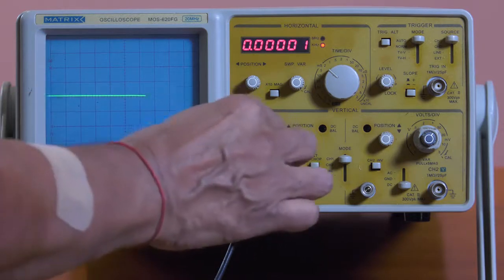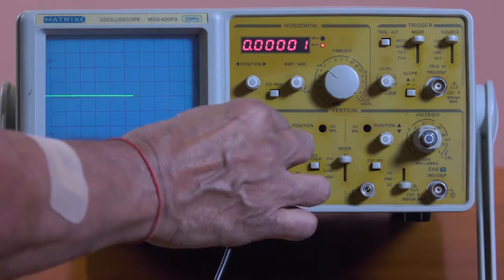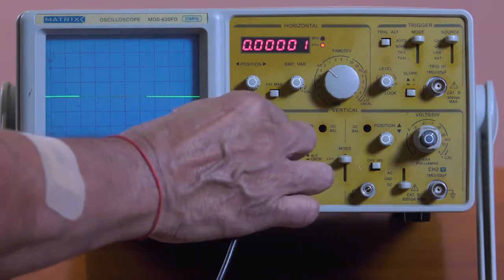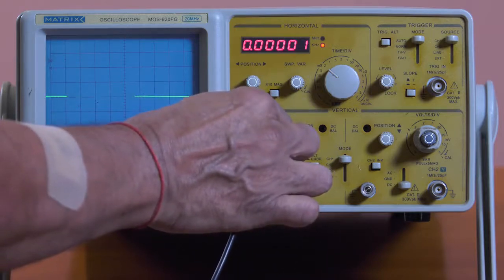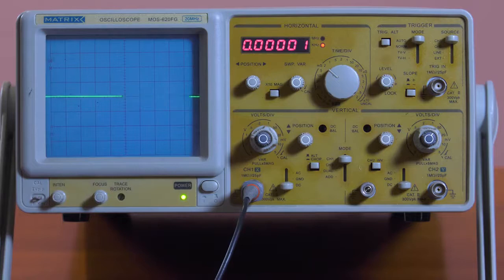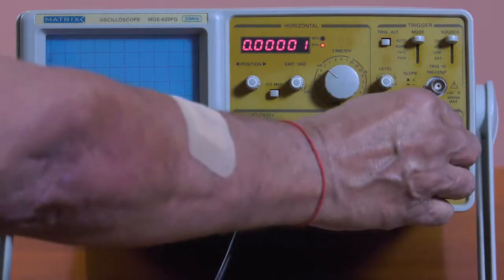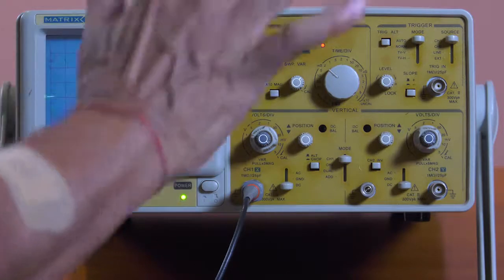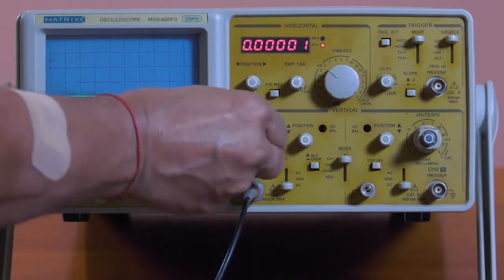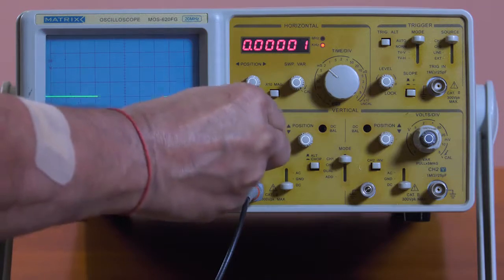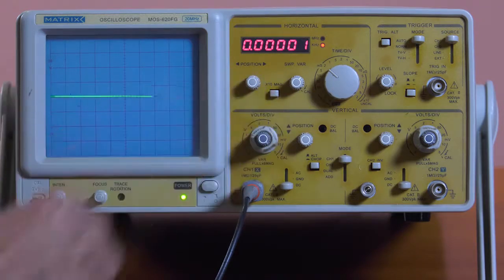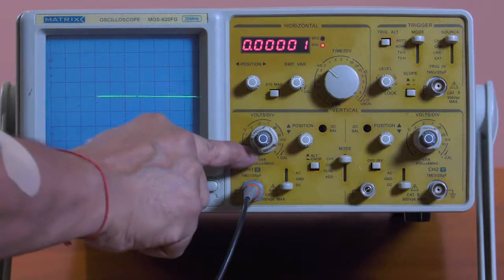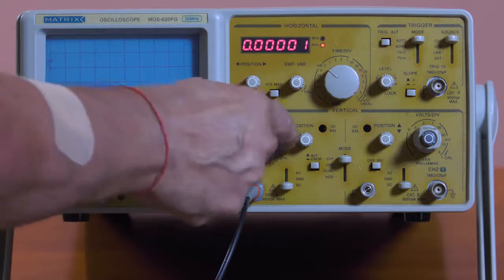Now, it's important to always calibrate your oscilloscope. We use this small gray button here. Listen for a click. That is in most cases calibrated. Channel 2 also has one. If you get it into that position, chances are that it's calibrated 100%. You might have to make slight adjustments by bringing it back and forth, but for our exercise, that's not going to be necessary.